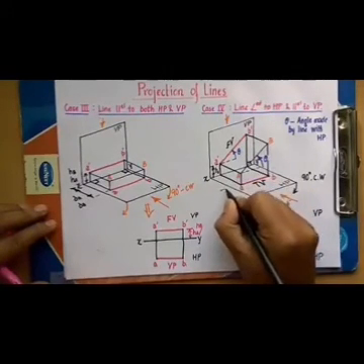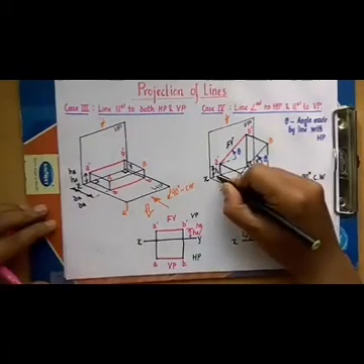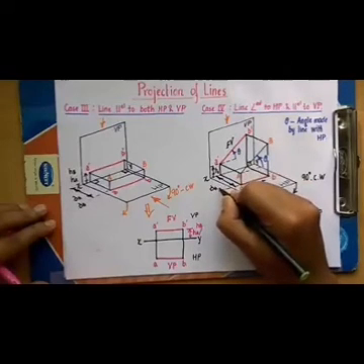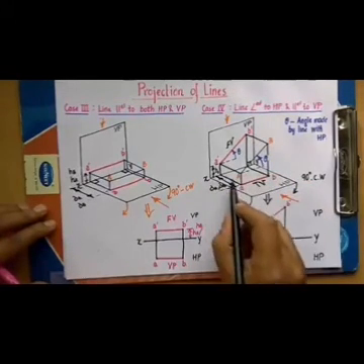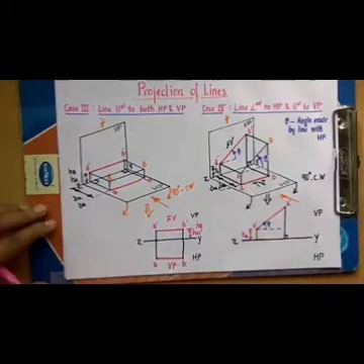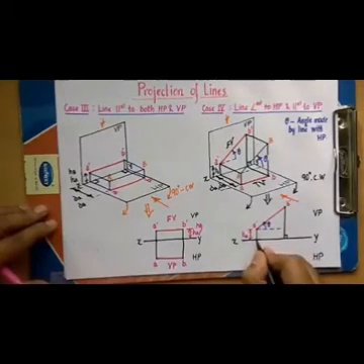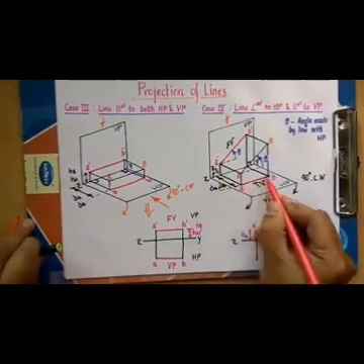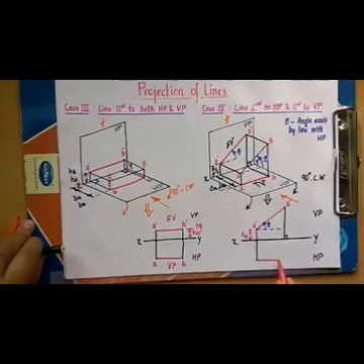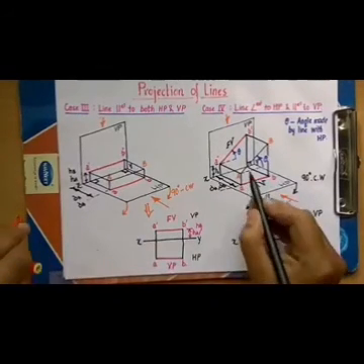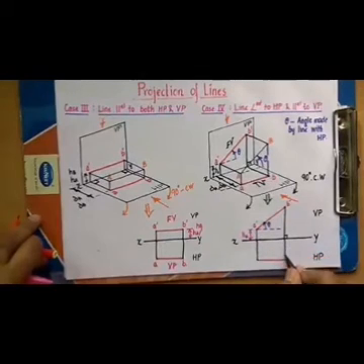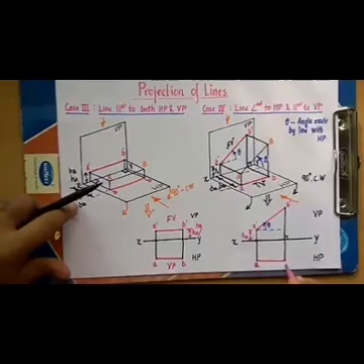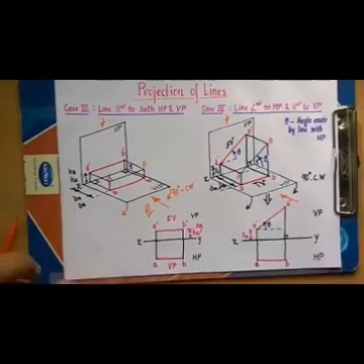This is what you call the distance of this point from the vertical plane. This is what you call DA. You can also call this DB. Both the distances are the same since the line is parallel to the vertical plane. So let's have this distance over here, and so we've reached here. This is going to be the top view. Let's draw this top view. That's it, guys. Now I'm going to bring this point downwards here. Finally we have A and B, and that's what you call the top view.